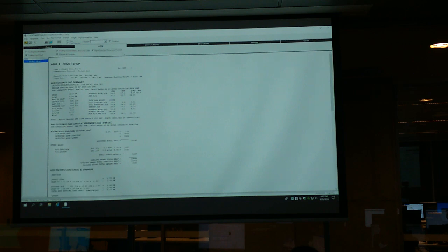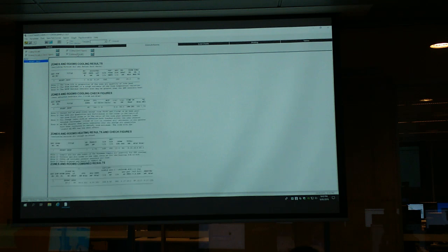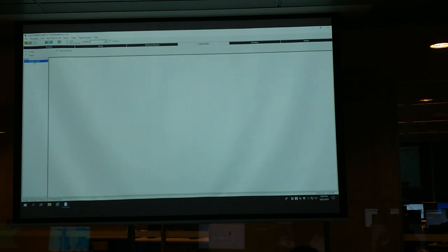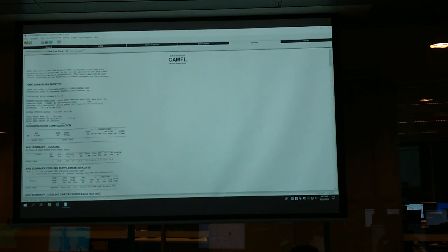Click all the items, and then click on the name of the air handling units: cooling results, heating results, cooling results checking, combined results, load charts, cooling load, heating load, data iteration in the calculation, and then print. Okay. After here, I think you will need to save these documents in PDF, but as far as I know, I can't save.